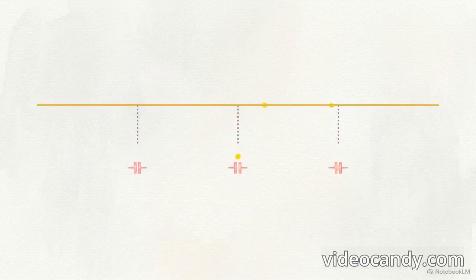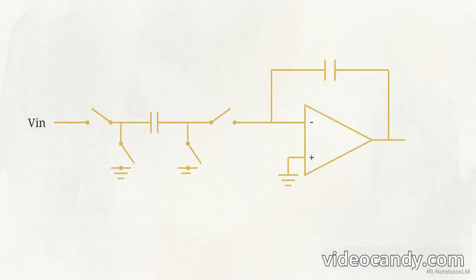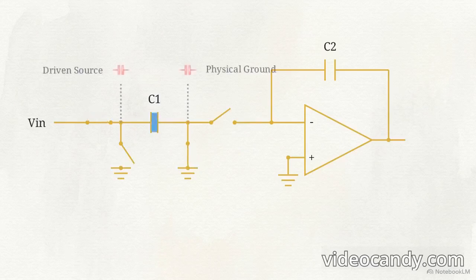There is one final physical threat to resolve. The actual silicon routing on the die and the bottom plates of the capacitors naturally create their own parasitic capacitance with the substrate. Left unmanaged, that invisible parasitic capacitance will passively absorb signal charge out of the loop.